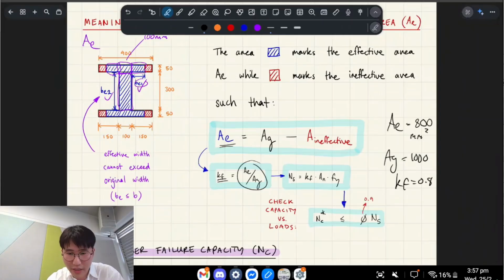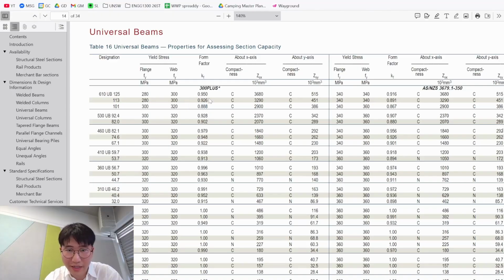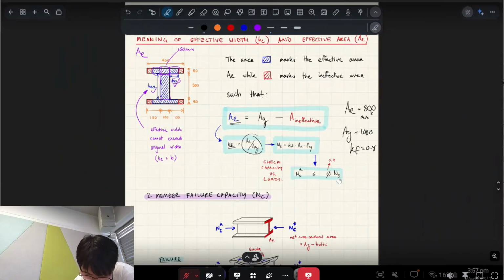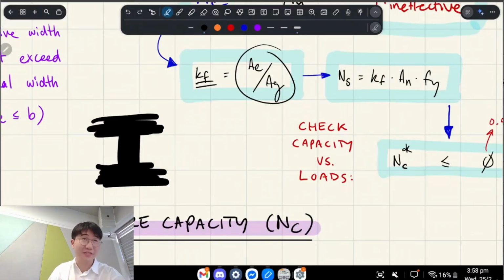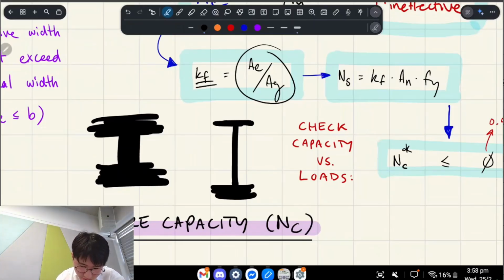So what they're actually trying to do when they're finding the ideal dimensions of these shapes is they want to keep this number as high as possible, but not over design it as well. Because you could just have an enormously stubby I-beam, right? But that's super impractical because it's heavy and you're wasting a lot of material. So they want to keep it as thin as possible while not buckling as much as possible. So that's how they ended up finding the perfect shapes. Do you know what I mean?